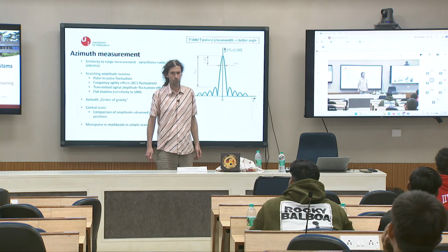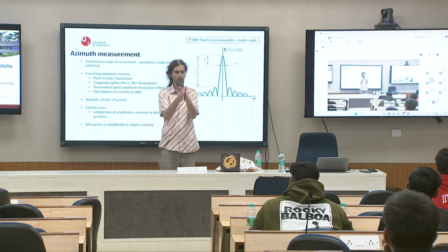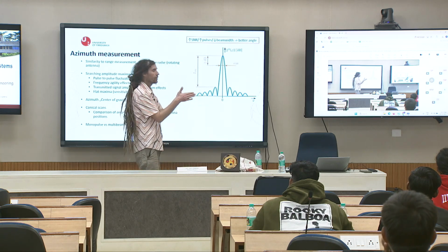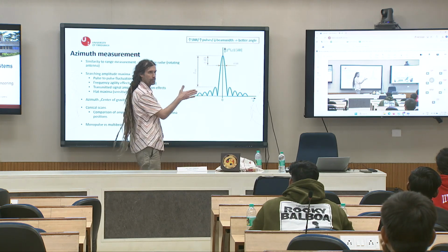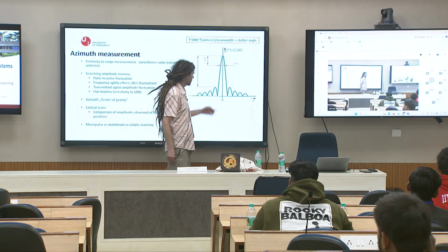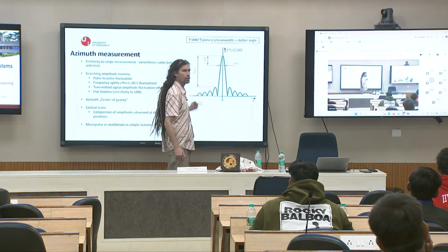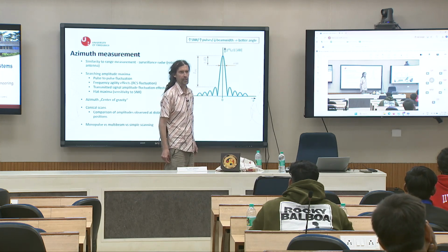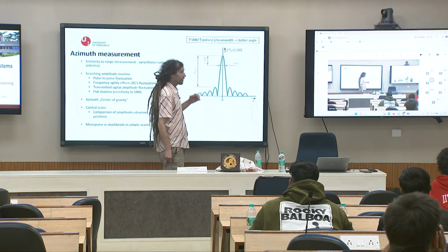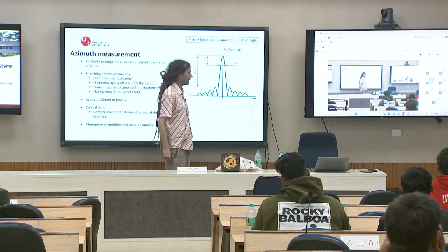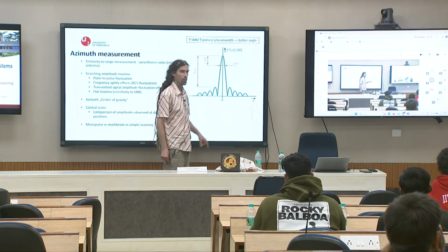And again, what do you want? Slimmest, narrow, thank you. Narrow is better because I can easily recognize the target. And this we don't want. We want 0, but it is not physically possible. It is theoretical only. And these sidelobes of the antenna cause a very big problem. Why?